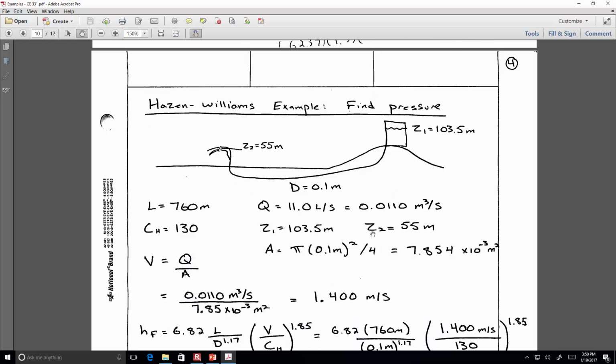That's a great question. The last example we're going to work today compares the two, and it shows that the Hazen-Williams equation is easy, but you sacrifice some accuracy. So for instance, when we're using WaterCAD or WaterGEMS for design, we don't care if it takes the computer a few extra cycles to converge on a solution for f. And so we'll always tell it to use the Darcy-Weisbach equation for calculating its head losses. But if you've only got 2.9 minutes to come up with an answer, then the Hazen-Williams equation will do a great job, and it's pretty direct.